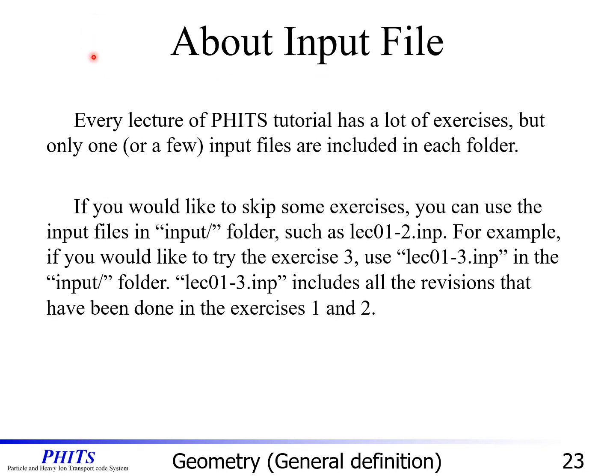Here is shown about the input file. Every lecture of the PHITS tutorial has a lot of exercises, but only one, or a few, input files are included in each folder. If you would like to skip some exercises, you can use the input files in the input folder, such as LEC1-2 INP. For example, if you would like to try exercise 3, please use LEC1-3 INP in the input folder. This input file includes all the revisions that have been done in exercises 1 and 2.